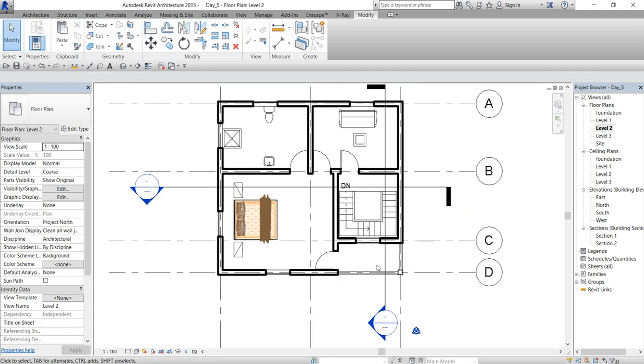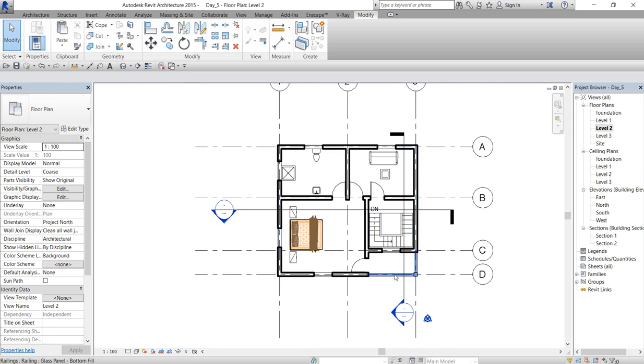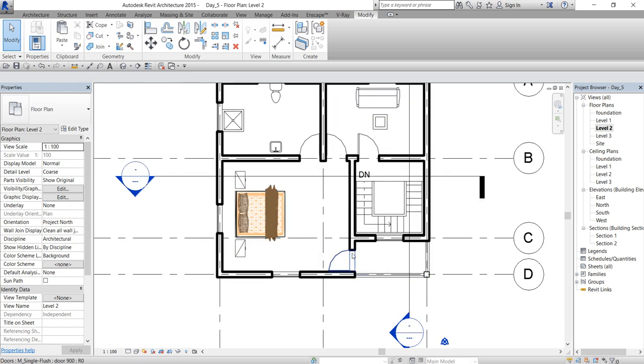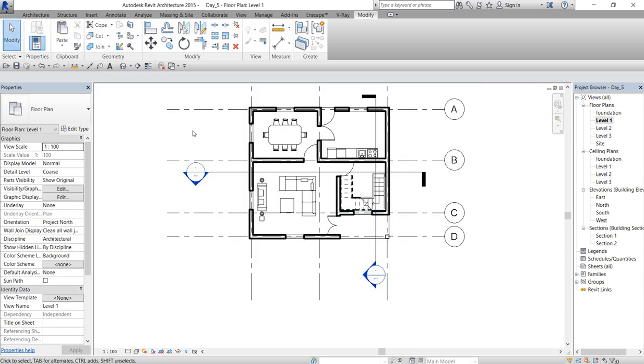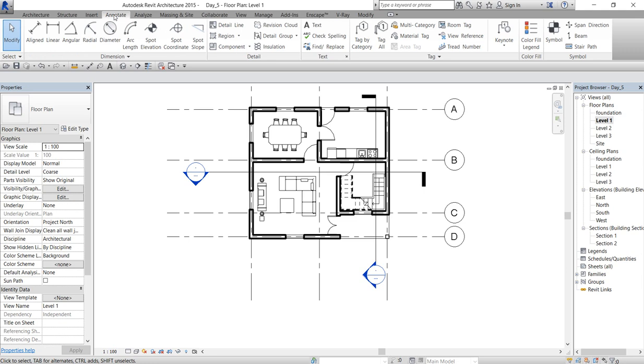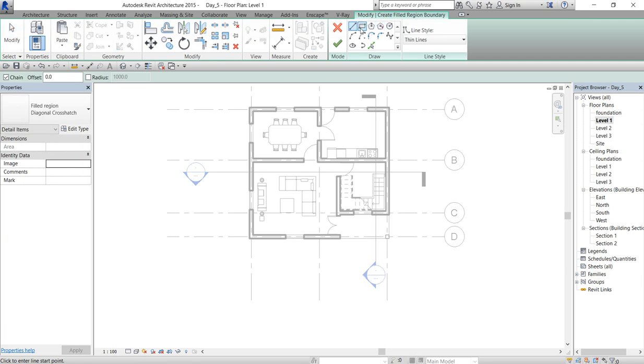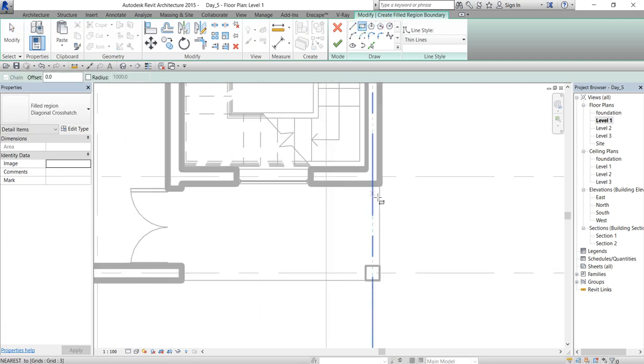Now, like graphic representations, all of us, we don't like the way the space will just be empty. So we like putting some certain patterns. So what we do here is that you click on Annotate, click on Region, click Region by Fill, then you draw.